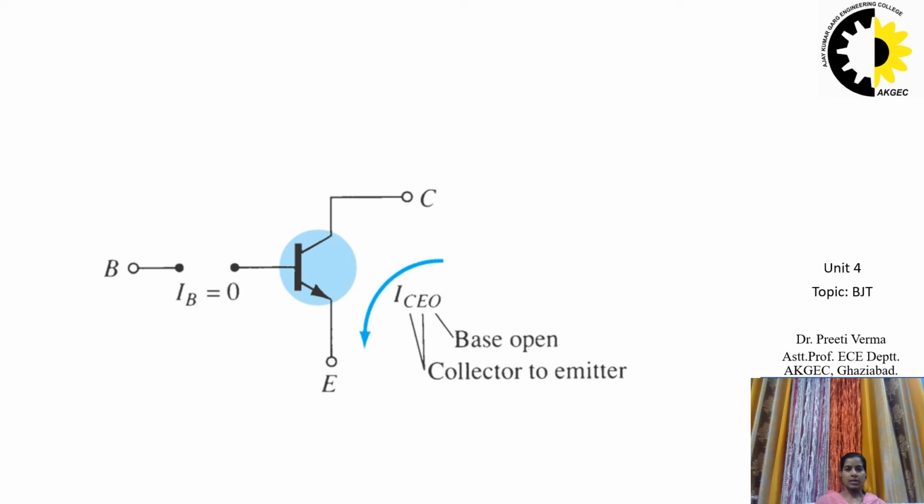For germanium transistors, however, cutoff for switching purposes will be defined as those conditions that exist when IC is equal to ICBO, that is collector to base current with emitter open circuited. This condition can normally be obtained for germanium transistors by reverse biasing the base to emitter junction a few tenths of volts.